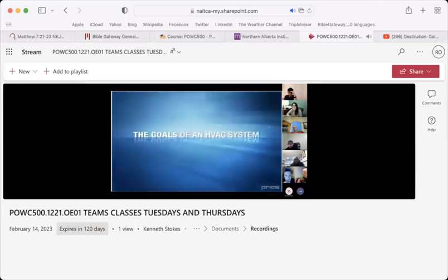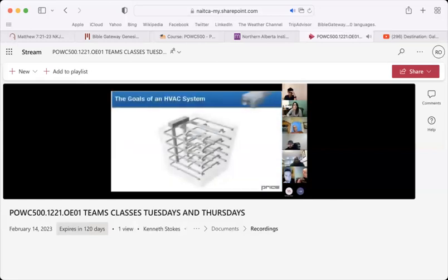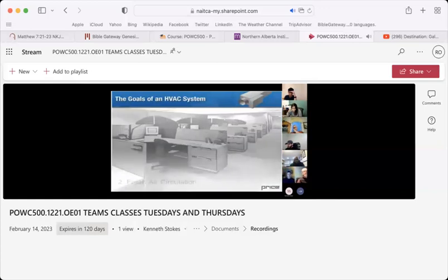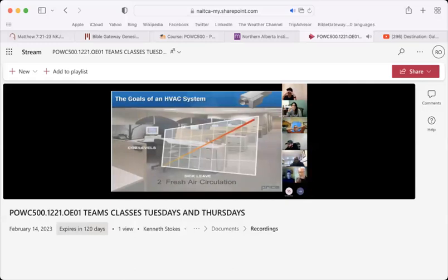The goals of an HVAC system. When examining the design of an HVAC system, we must remember the various roles that the HVAC system plays. We all know that when we're cold, we turn the thermostat up for more heat, and when we're hot, we turn the thermostat down. So the HVAC system keeps us comfortable by adjusting the room's temperature. But equally important, the HVAC system must keep occupants comfortable by supplying fresh air to a room. If we introduce a significant proportion of fresh exterior air and alleviate carbon dioxide buildup, occupants experience better health and performance gains. Studies have shown a direct link between CO2 levels and short-term sick leave in office workforces.